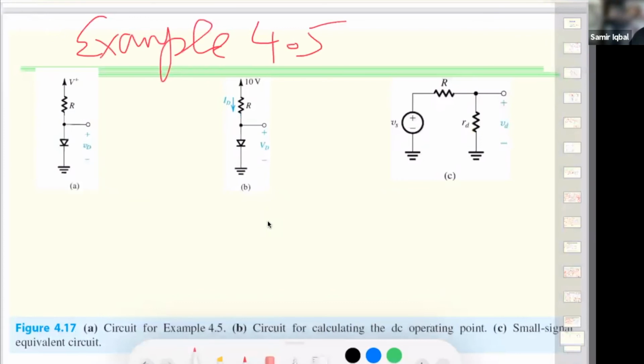So the statement is that the circuit has R equal to 10 kilo ohms. The power supply has a DC value of 10 volts, on which is superimposed a 60 hertz sine signal of 1 volt peak amplitude. This signal is an imperfection in the power supply design.